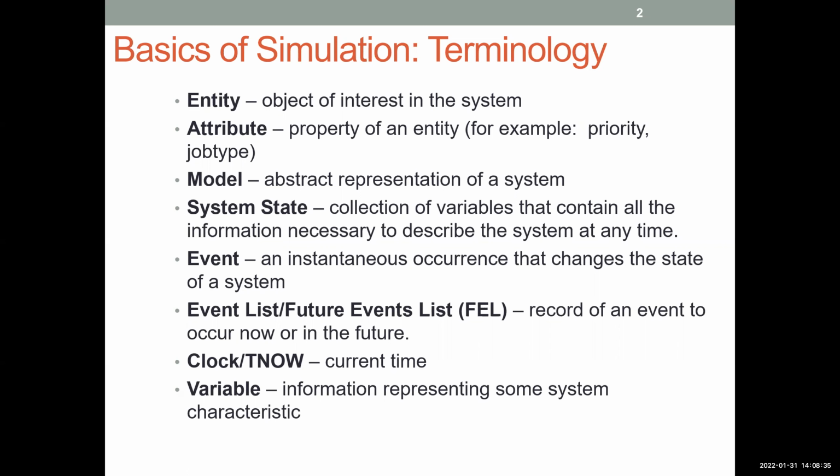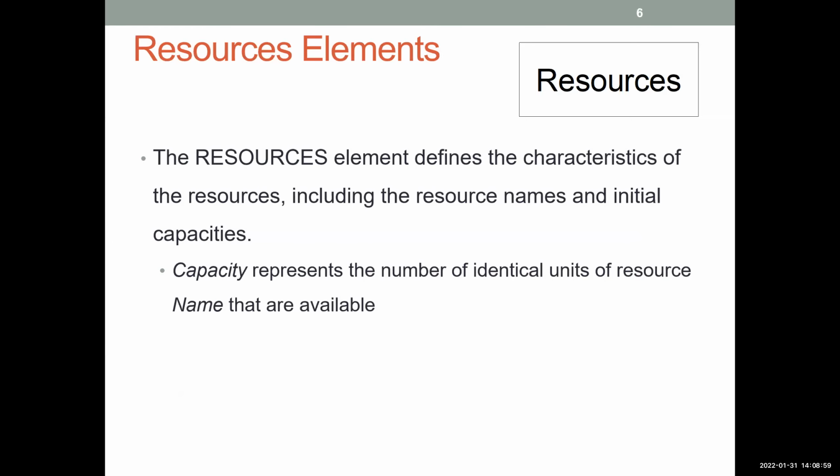Once you assign an entity a part type, that's going to follow the entity through the duration of the simulation. So you can use that information. Let's say when this entity arrives to a specific block, you can call that entity, and if you want to collect statistics about that part type property, you can do that. So we'll see how that works today.